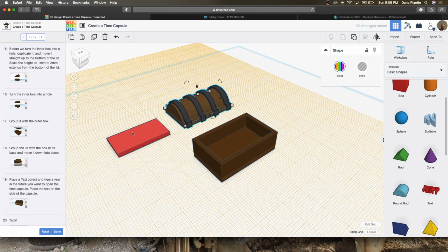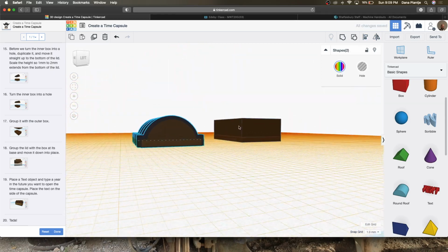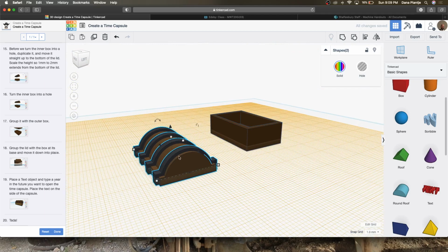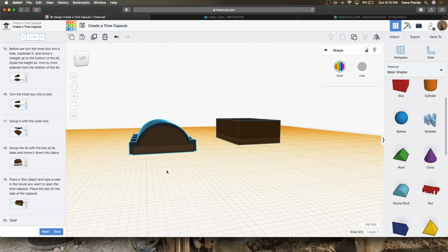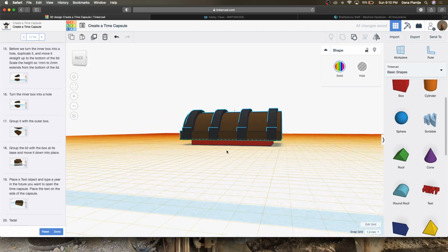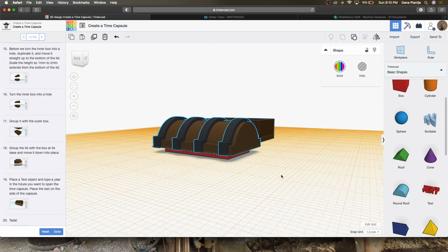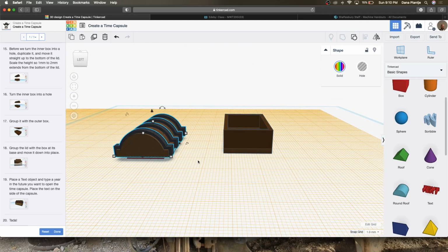and now when I take this new object and my lid, select those, and I align these, it's using the top of the new object as my work plane, so that now these objects, when I take the lid and hit that D key, watch it right here, it's below the work plane. When I push the D key, it's going to lift it up, and it's right on top of my object. So now I could group these together and join them as one piece.